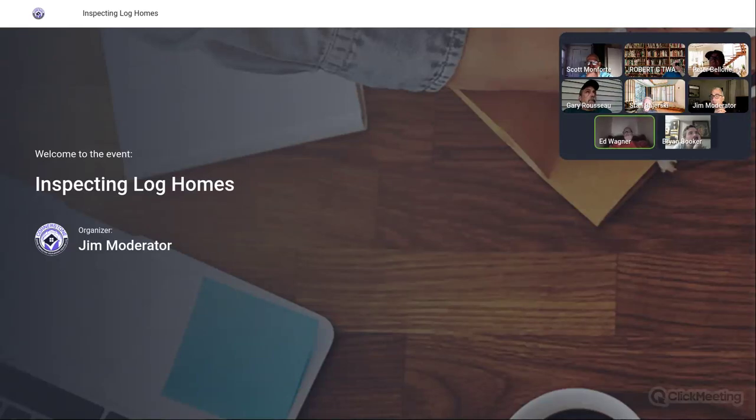I have seen what you've talked about, the too close to grade, and the bottom row of logs are usually rotted out. You can sound them with a rubber mallet so you don't dent the log. I've been using infrared forever, which doesn't always help, and it takes me longer and it's a little trickier. I agree. I was nervous the first one I did. I didn't know what I was doing.